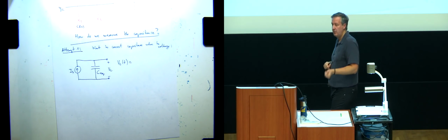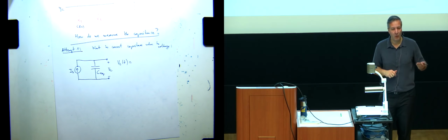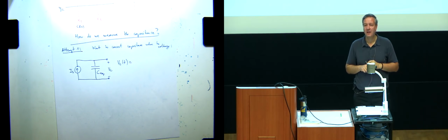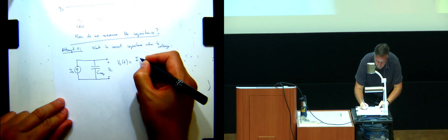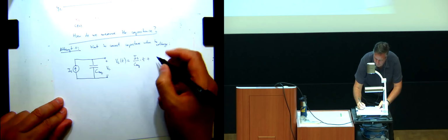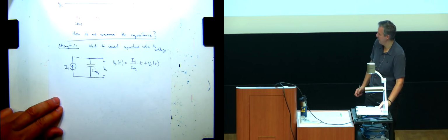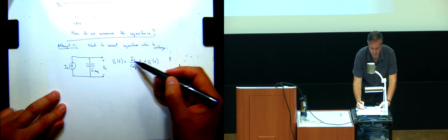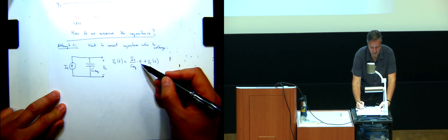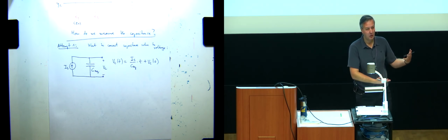And the capacitor current was a derivative of voltage, so that means that the voltage has a constant slope. Yes? Okay. So this is the equation. We have a constant slope that's proportional to current, inversely proportional to capacitance, times the time, plus Vc of 0, so that's some initial voltage.